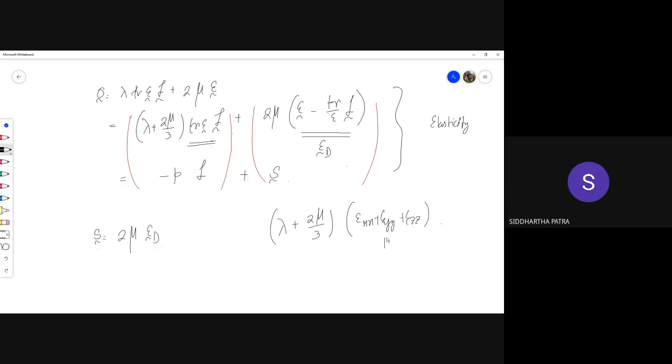And I am sure that you know that this actually represents the volumetric strain. Why volumetric strain? Let's say you take a brick of some sort, and the new volume after deformation is Lx times (1 plus epsilon xx), Ly times (1 plus epsilon yy), and Lz times (1 plus epsilon zz), Lx, Ly, and Lz being the dimensions in the x, y, and z direction.